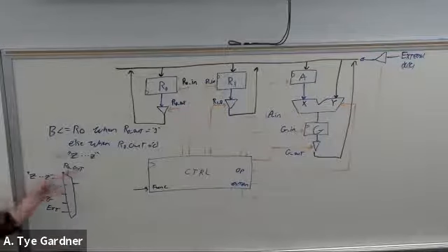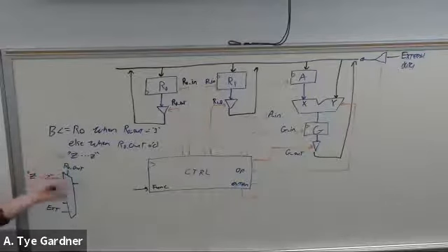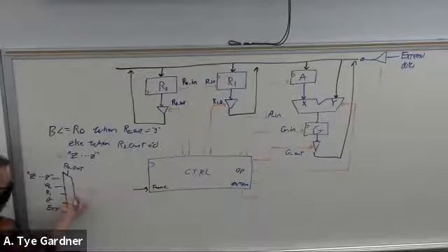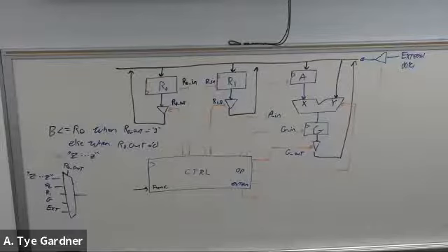And then I could just add control signals, which could be one hot or controlled however you want. And now I have a mux that is guaranteed to never assert more than one of these onto the bus signal. If you want access to the bus, you have to come through this. And if I'm not driving the mux, then I just choose 0, 0, and I assert Z's. I'm not driving that bus at all, and it's just floating, which is an option.